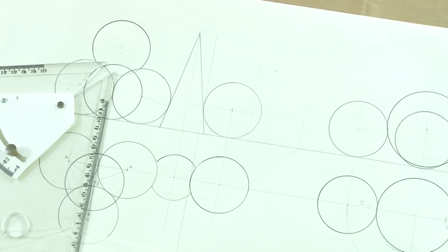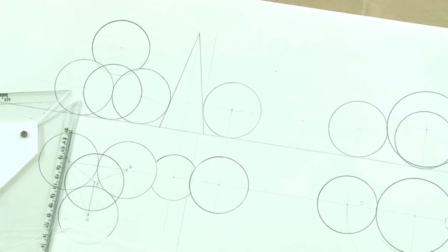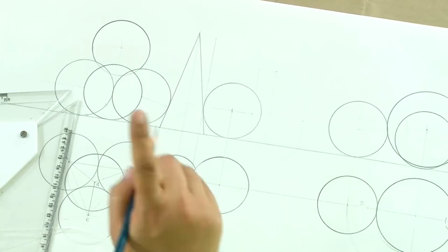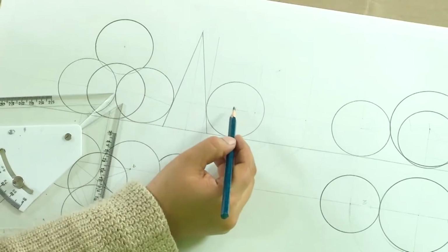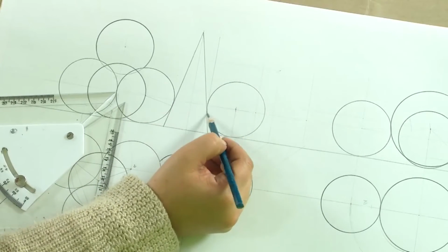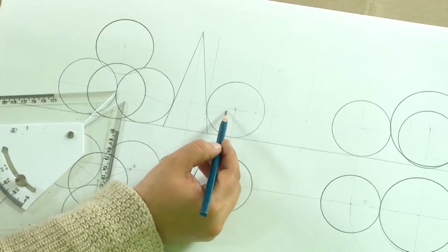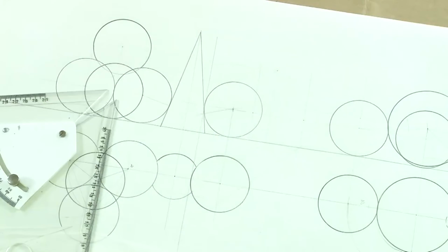Similarly, you could make the combination of spheres with any solid for that matter. The only thing we have to keep in mind, always remember, is where is the center of the sphere. And always remember that the sphere will be using one of the surfaces of the cone, or whatever solid, as a tangential surface. So, whenever we make this, we will have to take the perpendicular bisectors. This was one tangent. We could take the perpendicular of this and the perpendicular of that, and wherever they meet is the center of the sphere which we are going to get. So, this is how you will be able to locate the centers and draw any combination of spheres.